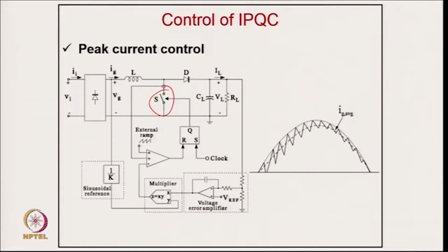Of course, taking a MOSFET, the very purpose is that you can go to quite a high switching frequency. People even work this converter up to 100 kilohertz. The advantage of going to high switching frequency is that the size of the inductor can be reduced, and the energy in the capacitor can be recovered at a very fast rate, but the size of the inductor reduces, which will reduce the size of your total converter also.